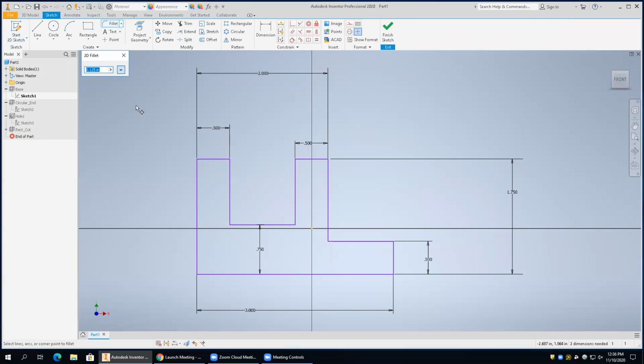and I'm going to change that radius to a 0.25 radius, 0.25. And I hit enter and it disappeared, so don't do that. So then you're going to come up here and select this guy and this guy. You should see it locks you in with a new radius. It also shows you those two symbols. That tells you those are tangent, which it should be. So we have a tangent constraint there. You also have a dimension there, which you can edit.